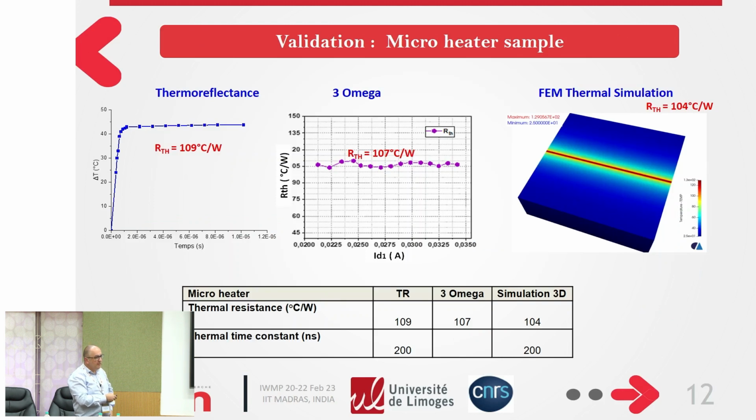We have validated this approach with a 3 omega method, which is very easy to use for resistors. And we have obtained a similar value for the thermal resistance.